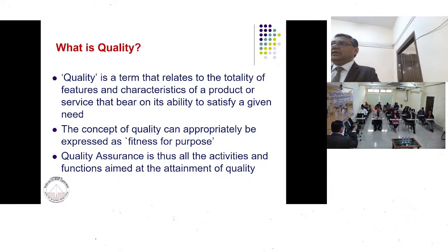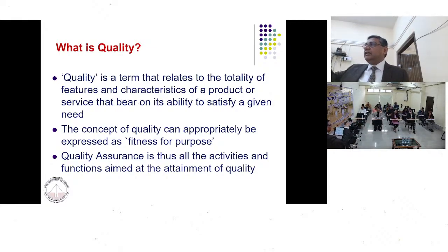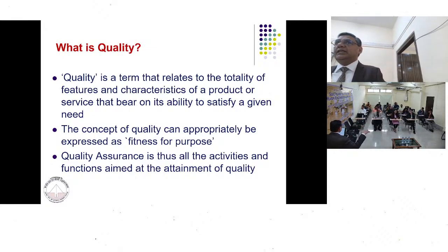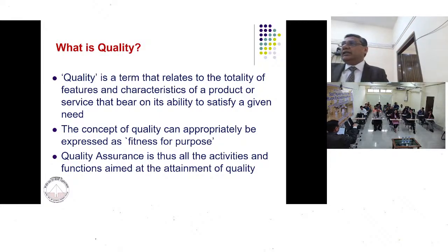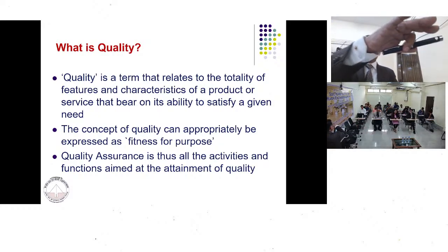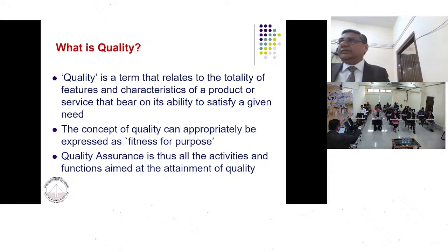Okay. So again I'll repeat. I have a construction team. I have a team who is looking after whether the construction team is working as per the correct procedures or not. I have another team which is known as the quality assurance, which is looking at whether the checklist of the quality control people are correct or not and whether the quality control people are taking due care and at those particular times and intervals they are doing their job or not. So quality assurance is something above the quality control.